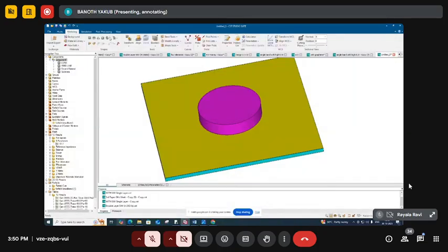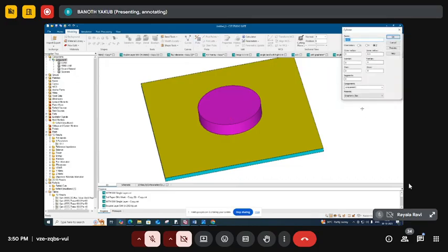After that, you can come to the modeling, select the cylinder, and just press escape. We are designing the graphene layer on top of the DRA. The material name is graphene, the radius is 12, then x center, y center, z minimum, z maximum.